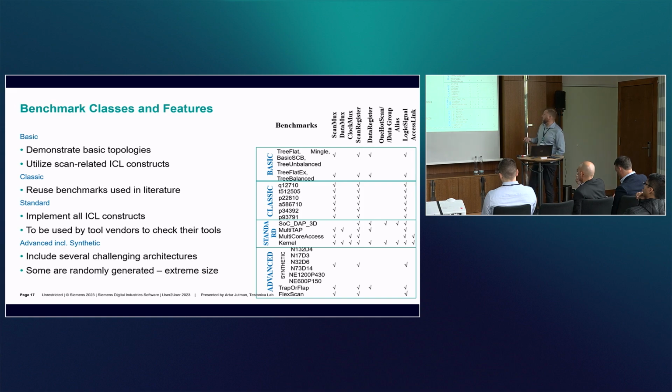Just pointing out that there are different ICL constructs in the standard. Some of them are typical; they would be present in each and every IJTAG design. Some of them are pretty strange, I would say, non-typical. Those benchmarks actually include all of those constructs. So if you want to validate your software against the standard, there is a way to do this using these benchmarks.